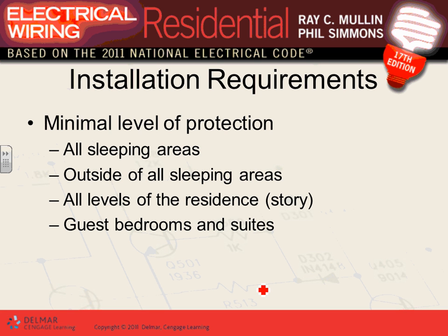Very important. Yesterday, guys, I told you number one, every sleeping area. Sleeping areas are not kitchens. Do you sleep in your kitchen? Could be. My son would. Sleeping areas are the bedroom, right? So every bedroom. Outside of all bedrooms, number two, that's hallways, right? The hallways outside the bedrooms require a smoke detector.